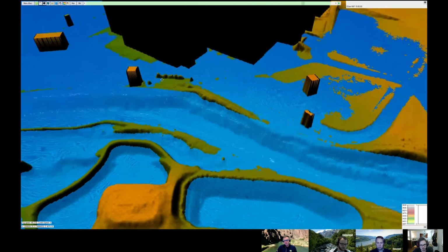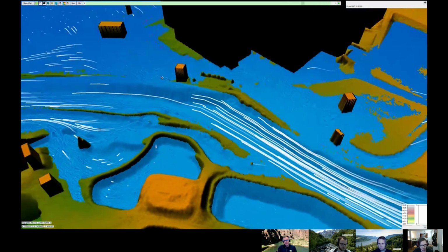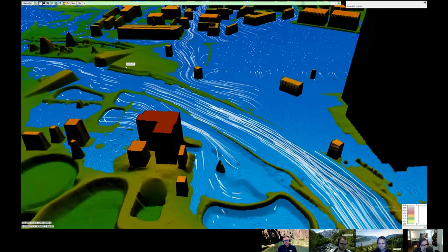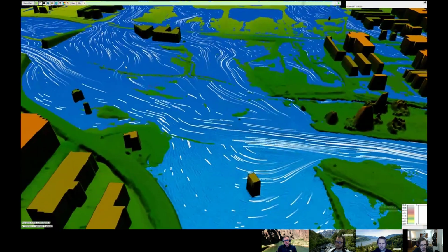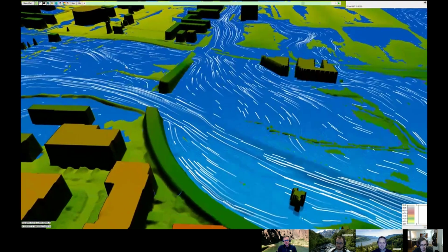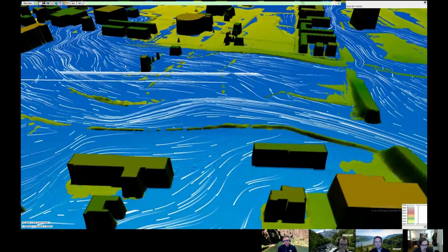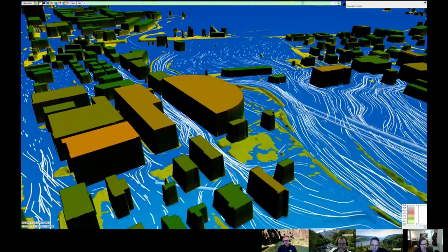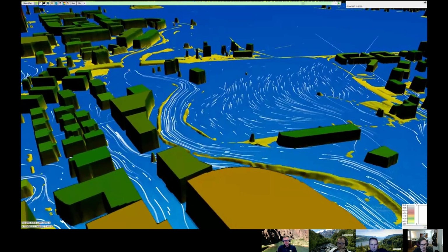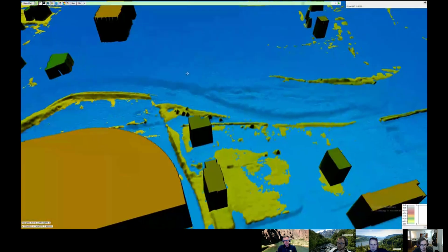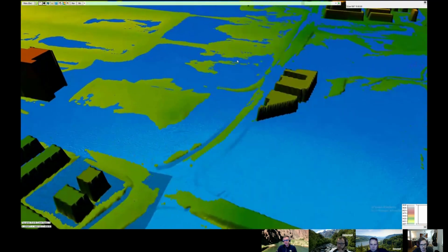And then particle tracing, you press the button here or you press P and you get particle tracing in 3D. And this actually updates while you move in space, unlike RASMapper. It's not perfect. The slower you go, the more it can keep up with loading while you're moving. So if you're making a video or something, you can always just speed up the video, right? I don't believe particle tracing works while you're animating, but only while you're flying around.